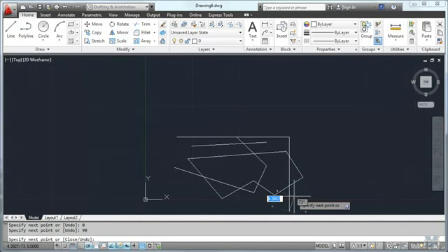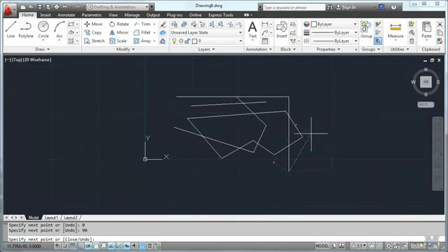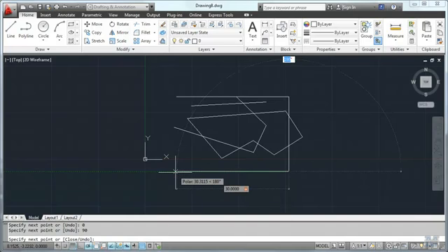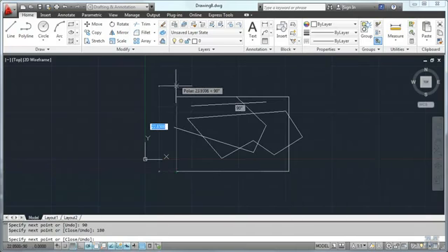I think I'll roll the mouse back a little bit and then pan it back up so I can still see it. Maybe we want to go back all the way across to 30 units again. Tab at 180, enter, and then back. I can also hit the C for close. If you're following the prompts in the lower left hand part of the screen, if you type C, L-O-S-E, or just type C, it'll close that into a box for me.